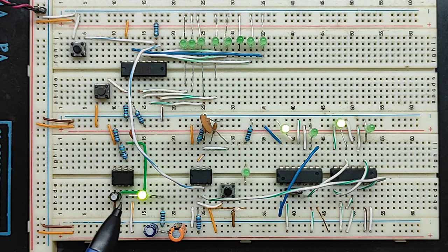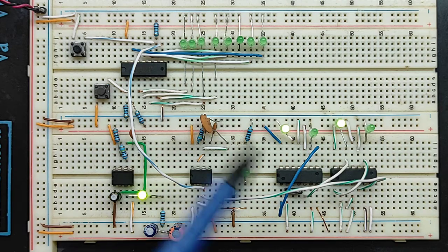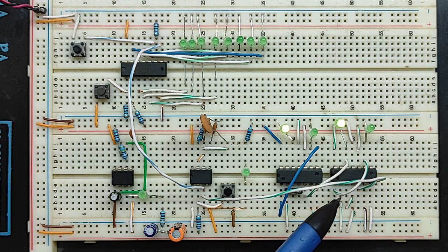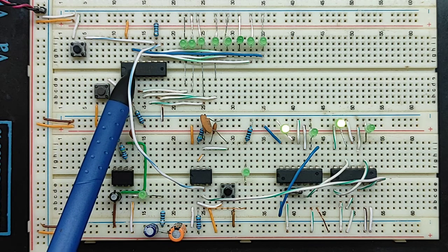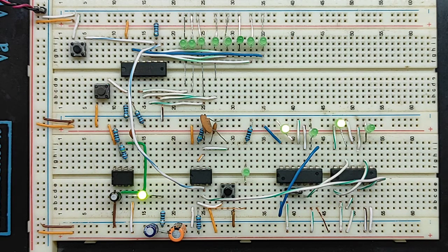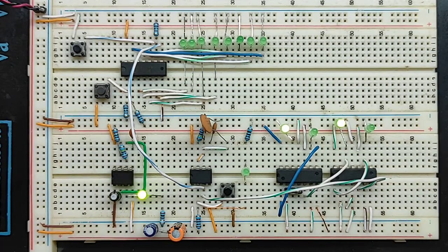See here, the computer clock is blinking on and off, and two other circuits are wired. One is a binary counter, another one is a shift register. We will discuss the shift register and binary counter in a future video. Okay, now come to the point. This is a 4-bit binary counter, also called a program counter. This binary counter counts 0 to 15 on the falling edge of the clock.